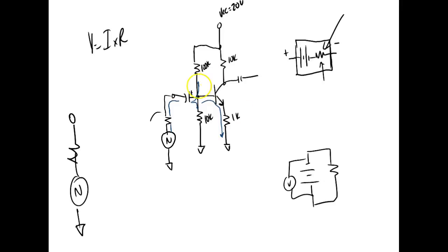So to calculate my input resistance, we'll call it Rn. This would be equal to 1 over 100K plus 1 over 10K plus 1 over Re times beta. Now remember, from the input point of view, the input sees that resistor times beta. And what law is this?